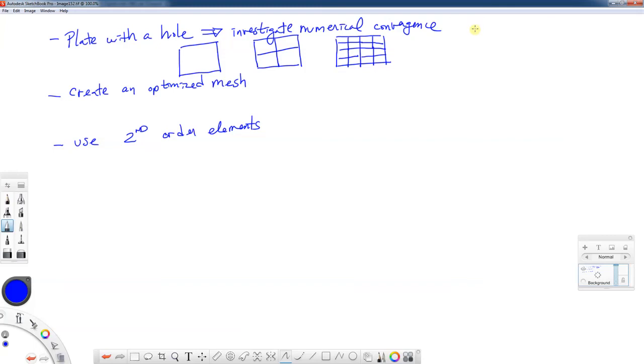In general, your convergence plots, like for ours, our stress concentration factor, as the number of elements increase, you start to see this level out. Now sometimes you can have non-monotonic behavior. It can go up, it can overshoot the stress concentration value that we thought it should be, and as we saw, we got 2.6 and we thought it ought to be 2.5 from the chart. Sometimes when you use way too many elements, you can over stiffen your structure. That's kind of an artificial stiffening.